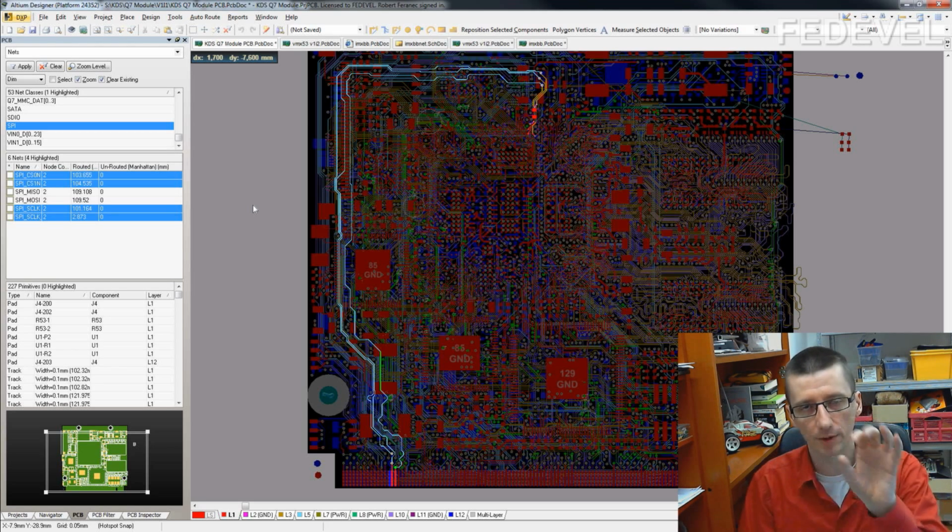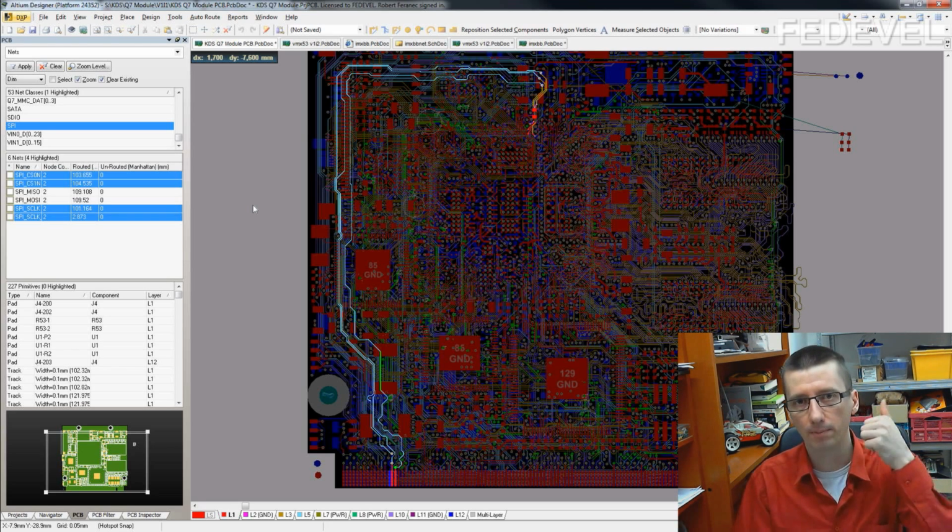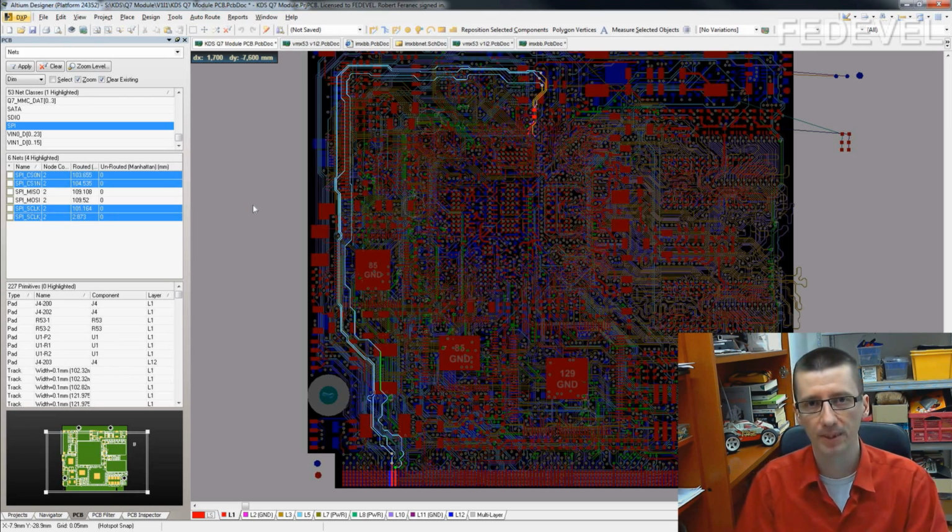So pick the most difficult violations at the beginning, and if all the other violations that are left are very similar, pick a corner and work systematically. Once this is done, all the pins are connected and there are no violations. And this is the end of phase 1 of PCB layout.